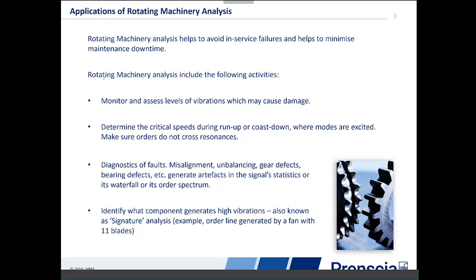And why would we want to do a rotating machinery analysis? First is probably to monitor and assess the levels of vibration which may cause damage. So you're recording the signal and you look at various metrics, and if these move with time, something's bound to occur.